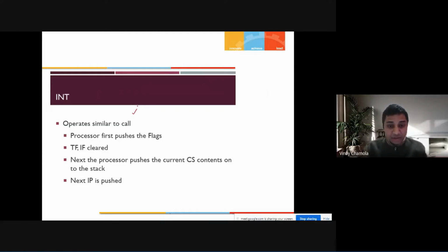So at that particular time, you may have certain flags. So this is where I am, say, before the interrupt being called. I have a particular CS:IP which is actually pointing towards the next instruction. As soon as I get into this interrupt, the CS:IP and so on and so forth, all of these may get changed. The flag registers may get changed.